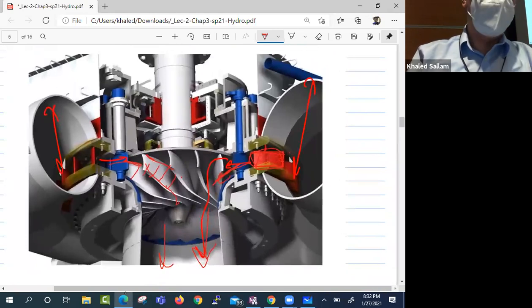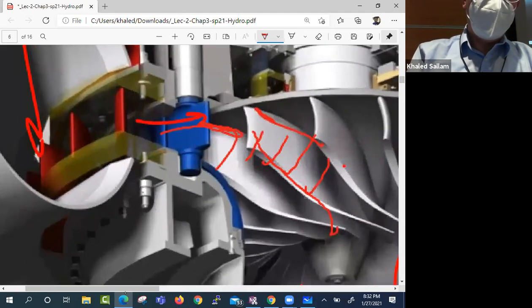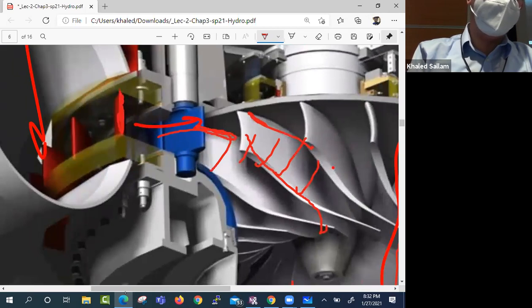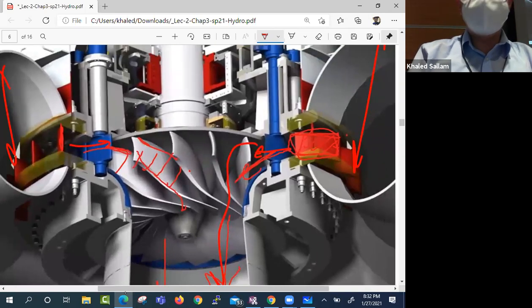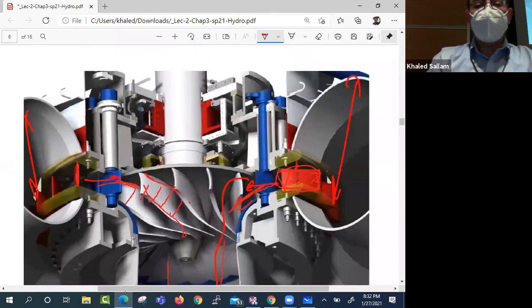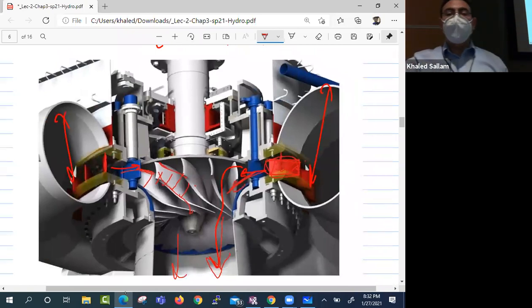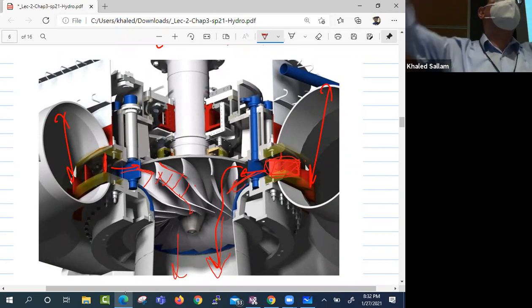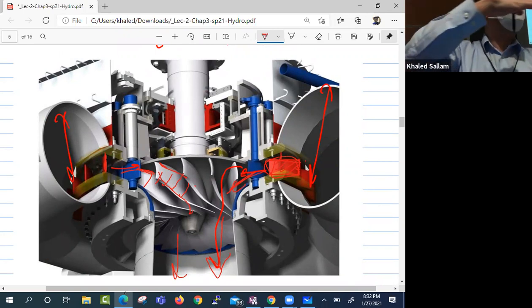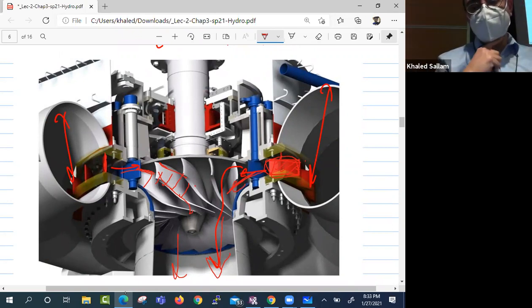Those are, actually it's red plates. What are those? Those are the stator. See, the flow comes in this pipe and it enters, you want it to enter radially. But rather than letting it enter radially like a bus stop or something, you want to twist it before it goes onto the rotor. So the stator twists the flow, right? And the rotor takes that twisted flow, uses it to turn, and lets the flow leave axially.